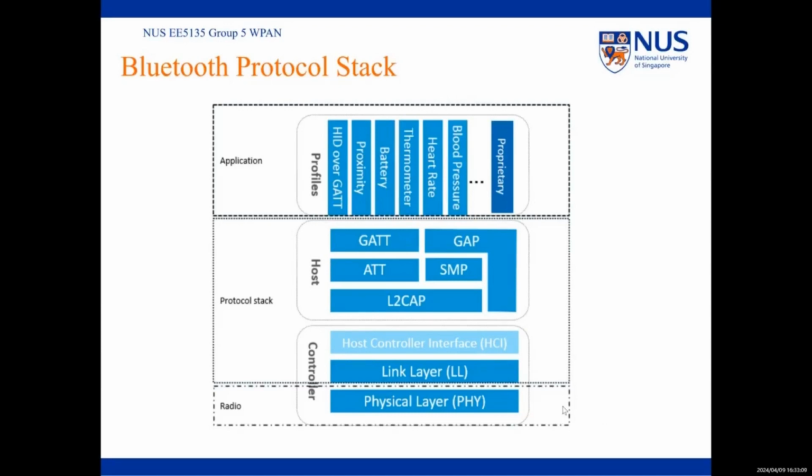And the attribute protocol, we can call it the ATT layer, is used to define user commands and command operation data. And the generic attribute profile, we can call it GATT, is used to standardize the data content in attributes and use the concept of groups to classify the managed attributes. Without GATT, the BLE protocol stack can also run, but there will be problems with interconnection.